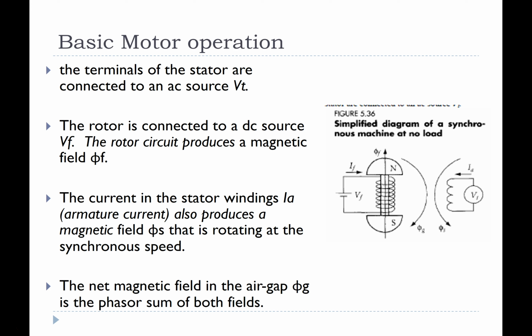On the other hand, when we have a motor, then we have the rotor energized still, but no mechanical input is being provided to it. We provide the voltage, the 3-phase alternating voltage on the stator side. That sets up our magnetic vector, and that magnetic vector interacts with the rotor field and pulls the rotor along, and that is what gives us the motor action. So that is the basics of the synchronous machine.